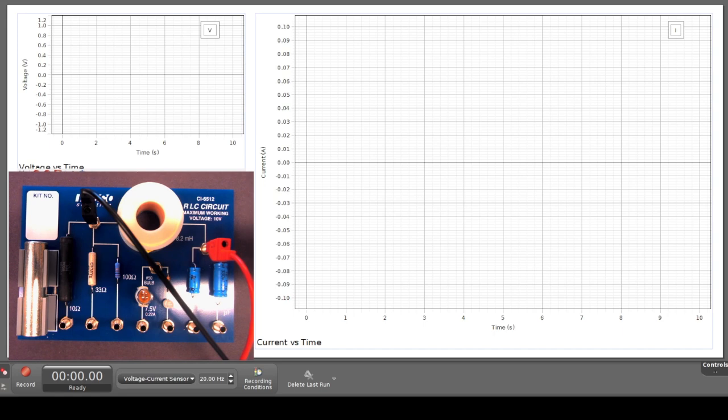Speaking of the time, if we know the resistance and the inductance, then we can simply calculate the time constant. In this case, it tells us the inductance, and we'll check to see how accurate that is, but we have no idea what the resistance is. So what I'm going to do is drive the circuit with a kind of square wave. It'll start at 0 volts, then go up to 1 volt, and then go back down to 0 volts. And I'm just going to have it repeat.